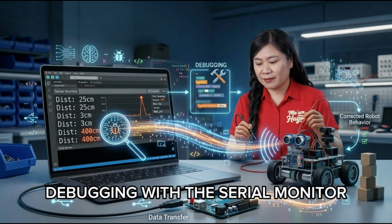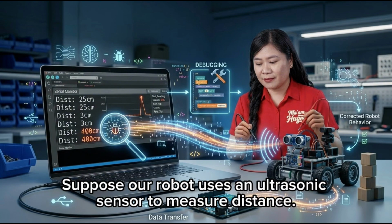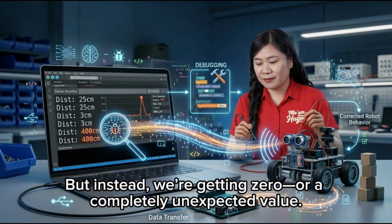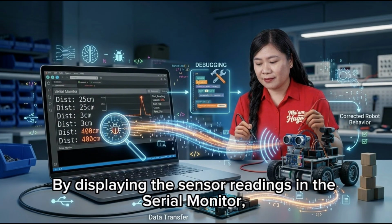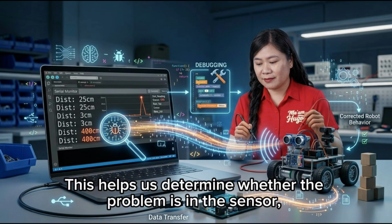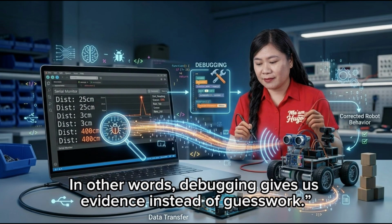Debugging with the serial monitor. One of the most useful debugging tools in many robotics IDEs is the serial monitor. Suppose our robot uses an ultrasonic sensor to measure distance. We expect the sensor to report a distance of 30 centimeters, but instead, we're getting 0, or a completely unexpected value. By displaying the sensor readings in the serial monitor, we can observe what the program is actually receiving. This helps us determine whether the problem is in the sensor, the wiring, the program, or the way we're processing the data. In other words, debugging gives us evidence instead of guesswork.